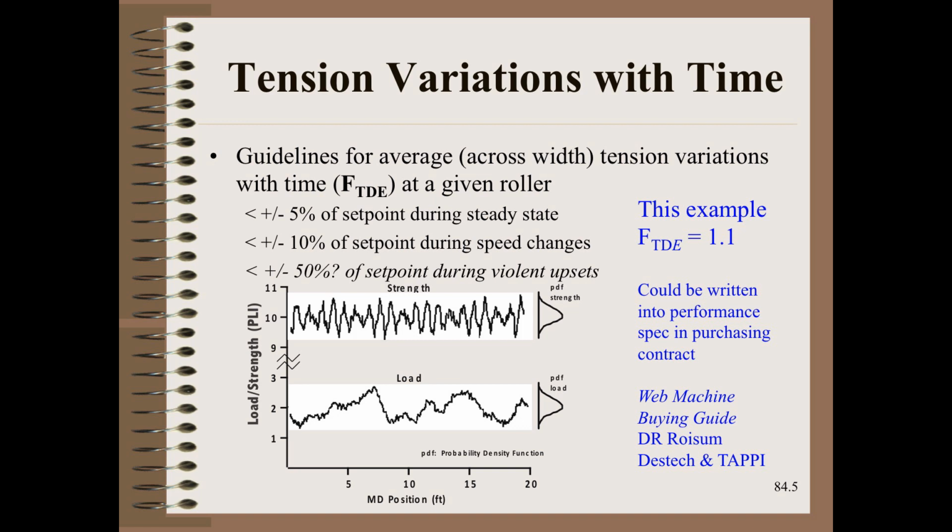Drive controls do not hold tensions perfectly. Some of this is inherent in the unavoidable following errors for PID controls. To this, we add many other sources of variations, including a less than optimally designed or tuned drive system.